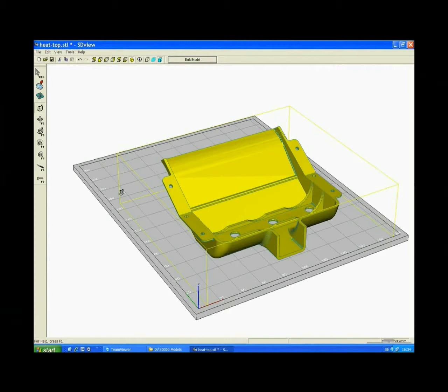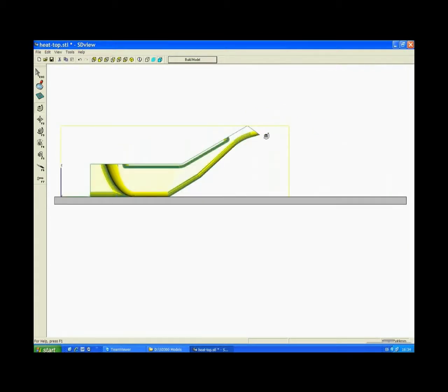This is a tricky example. It shows a geometry that includes a diagonal wall. This means that if a layer runs through this area and one attempts to peel it from this area, removing support material in an upward direction, the support material surrounding the part will then reach an undercut, enabling it to be peeled only in the downward direction.